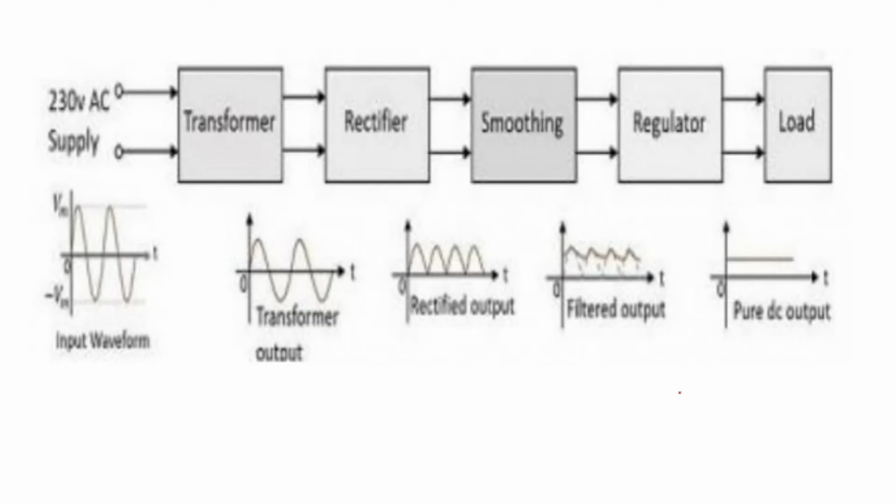Ultimately, if you see the concluded diagram of the regulated power supply, the first block is the transformer. This takes your main AC supply where the voltage is high, and converts it into a smaller voltage, but it is still AC supply. This is the step down process. The number of primary coils is more and the number of secondary coils is less, so you are reducing the voltage. Now this is AC only.